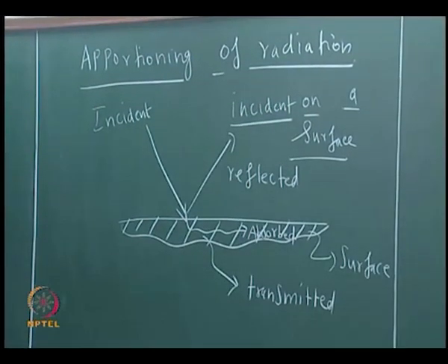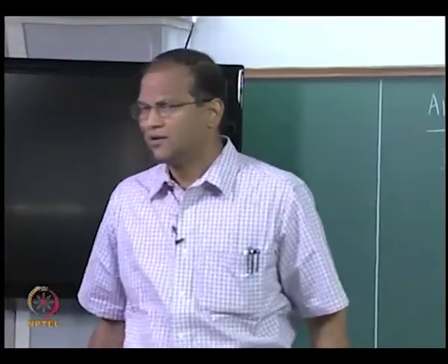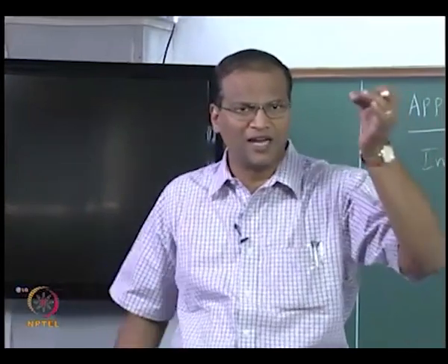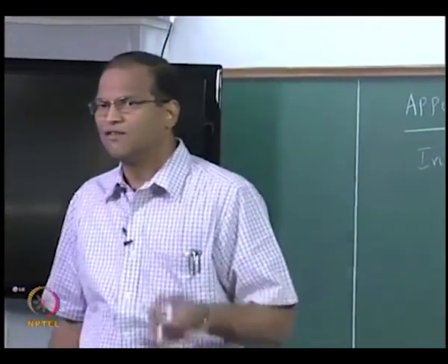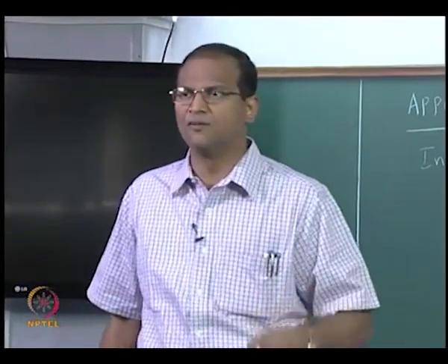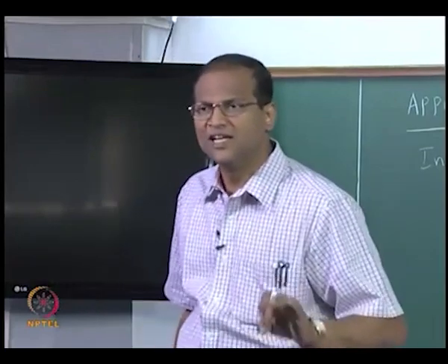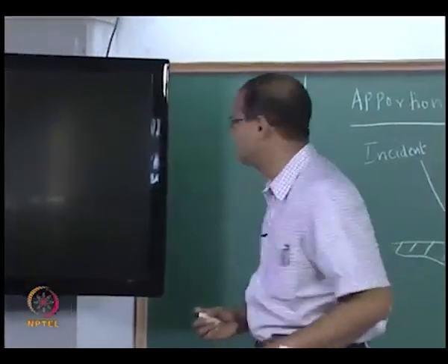So if you apply the first law of thermodynamics to this surface, don't worry about emission and all this. We are tracking what is happening to the incident radiation. Then from the first law of thermodynamics, mathematically we can state that incident radiation must be equal to the sum of absorbed, reflected and transmitted radiation.